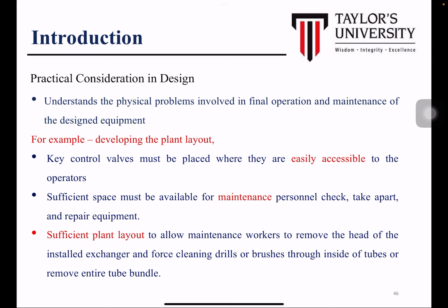Definitely we are not studying that now, but there are resources available where you can study how to design your plant layout. Sufficient space must be available for maintenance personnel to check, take apart and repair the equipment, right? Don't make it very congested.